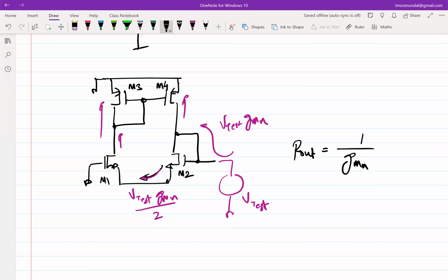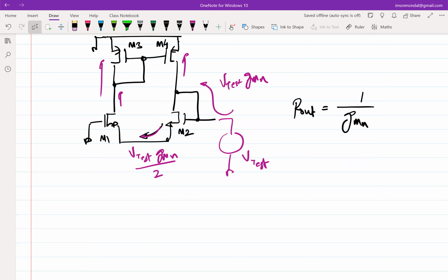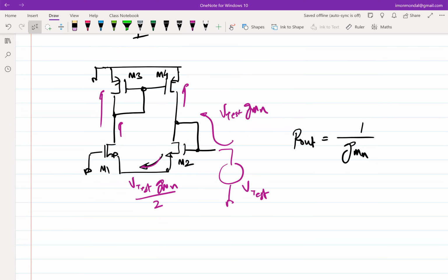Okay, so you can do it in another way, which is the symbolic way. So what was the symbol of this that we replaced it with, this diff amp? Okay, tell me what are the approximations? What did I neglect? GDS of M1. GDS of M1, fine. So is that a good enough approximation? So that's a good enough approximation. What else? Then for M3 it's a direct connection, right? 1 by GM. Fine.